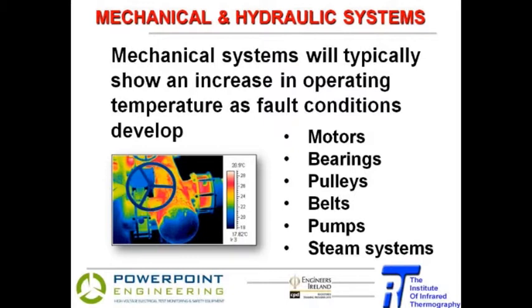You have to have a baseline, you have to start from somewhere. But now when you go back to that piece of equipment each time, you can get an indication of the health of that component or that whatever it happens to be, motors, bearings, pulleys, etc. Generally speaking, they will always show an increase in temperature as they start to fail.